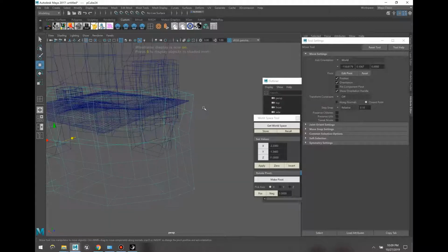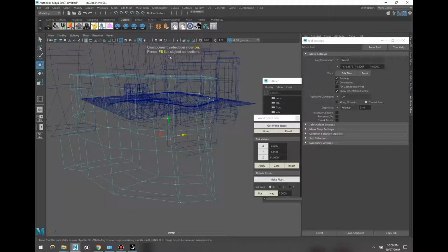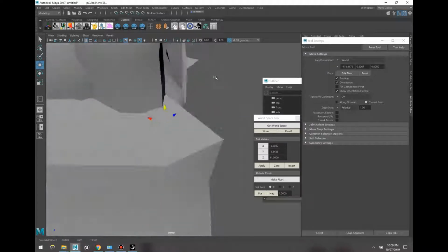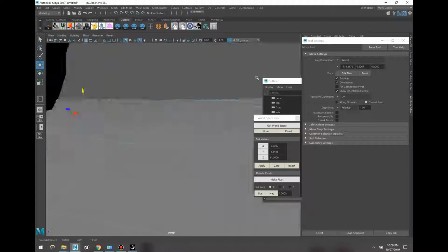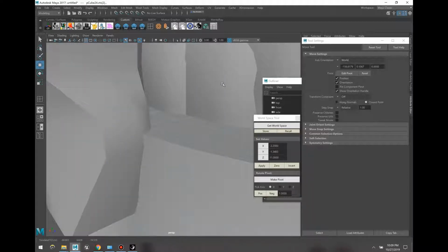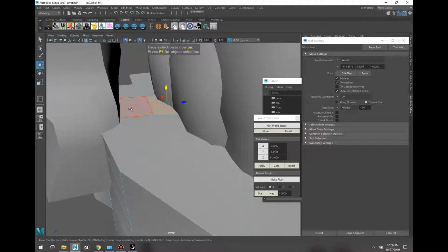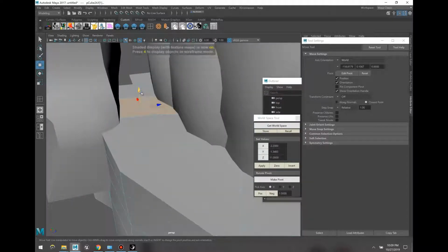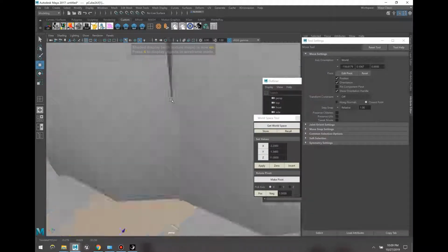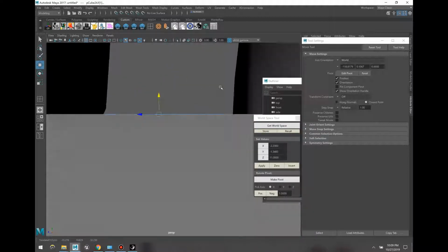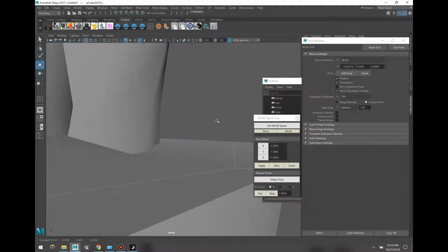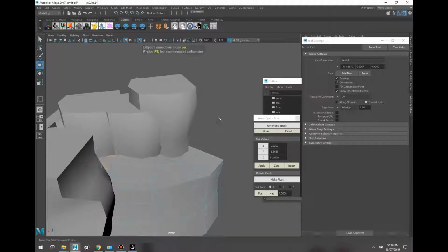You're probably thinking, hey, it's flat. But the good news is, because it's Maya, I just have to grab these verts for these faces, and we can go down a couple meters. So like that, we have a nice sloping down sort of thing. If I want to, I can even select these faces, put them up a meter. So it's like, oh, you have a little slope up, and then a reveal, and then there's the edge, and it slopes down. So that's a nice quick way to do it.